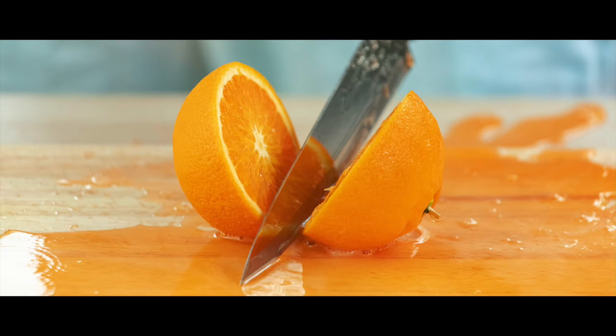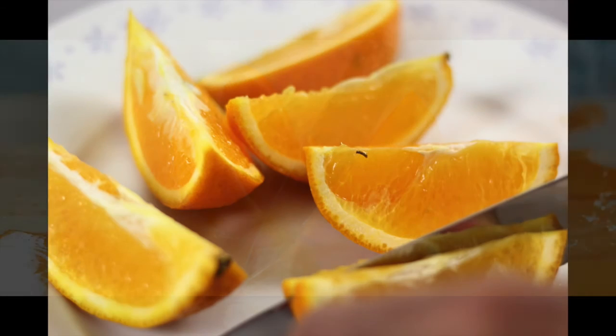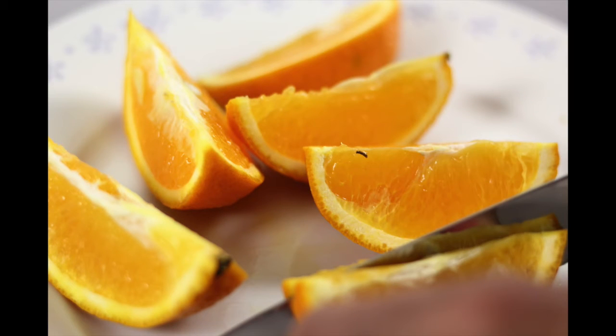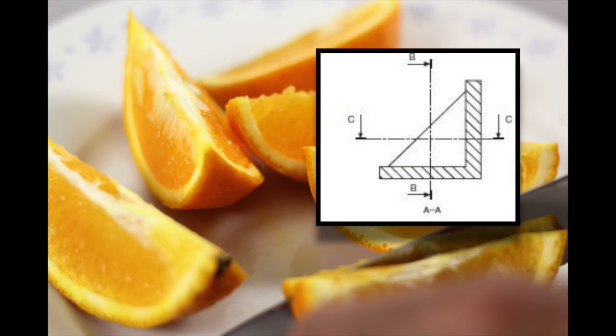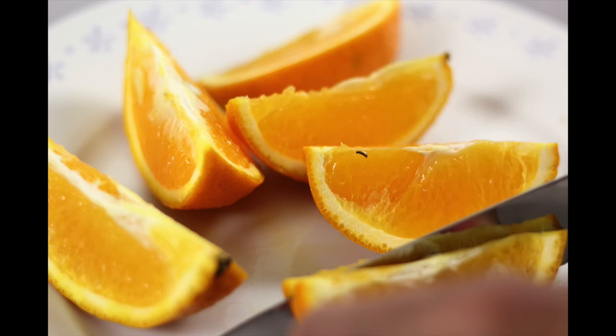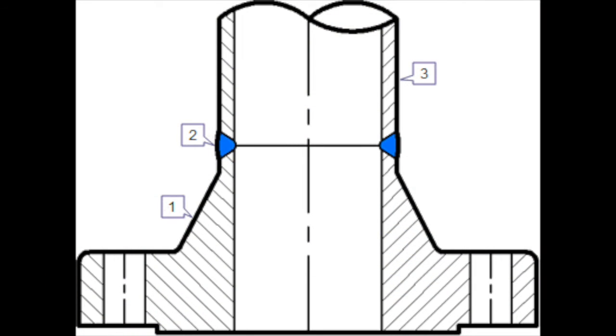By using a cutting plane line, the engineer can show what the inside of an object looks like. This is typically used when building a boxed object with much detail on the inside. There will always be an additional view that you can look at for the specific cutting plane line. If there is more than one cutting plane line, the engineer can communicate this by labeling them with AA, BB, CC, DD. Section view lines are used to communicate what type of material you are working with. There are different types of section view lines to illustrate what type of material is being used.